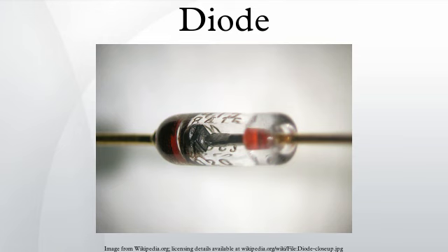carriers. Stabistors or forward reference diodes. The term stabistor refers to a special type of diodes featuring extremely stable forward voltage characteristics. These devices are specially designed for low-voltage stabilization applications requiring a guaranteed voltage over a wide current range and highly stable over temperature. Transient voltage suppression diode.